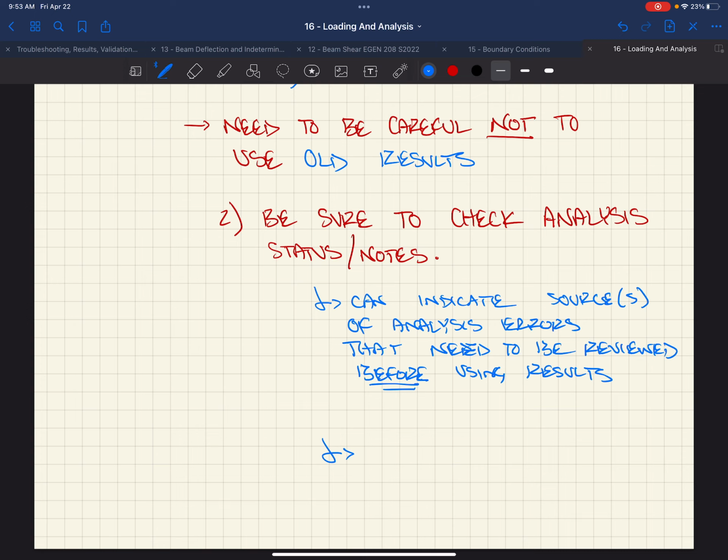Another thing that it checks, which it will run, is that it knows the materials you used, so it knows what the yield stress of that material is. So it figures out the stresses in all your members. And if a member goes beyond yield, it's going to give you a warning because we're assuming linear elastic, but the results you're getting assume it's linear elastic beyond the yield. In reality, it won't be, and so the model's not accurate. A lot of those things come up.